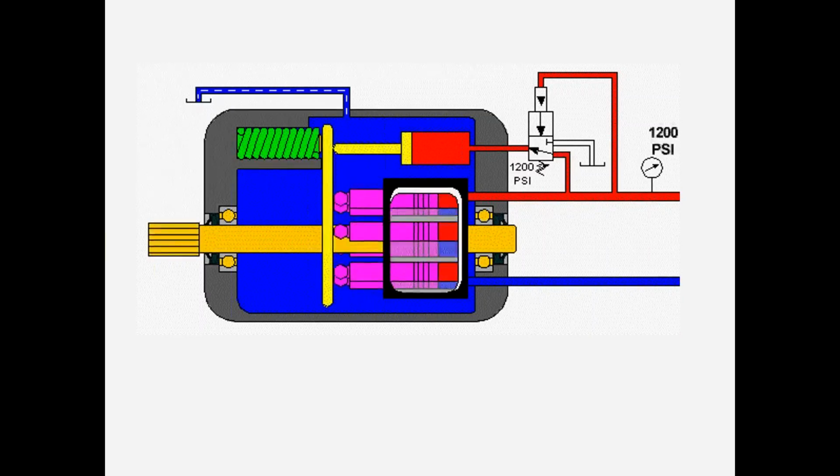Now here's the thing. If we did change the pump, that would still fix it, wouldn't it? Because a new pump comes with a new compensator that's not stuck. I mean, you still messed up, just nobody knows it. Well, one guy knows it. The guy who rebuilds your pump, he knows it. And of course, he'll call you up and he'll tell you that no, the pump didn't need to be rebuilt. It just had a little trash in the compensator. I've cleaned it out for you, and I'm going to send it back to you for no charge. Yeah, right. Now, what he's going to do, you're going to get a $4,000 paint job on your pump.